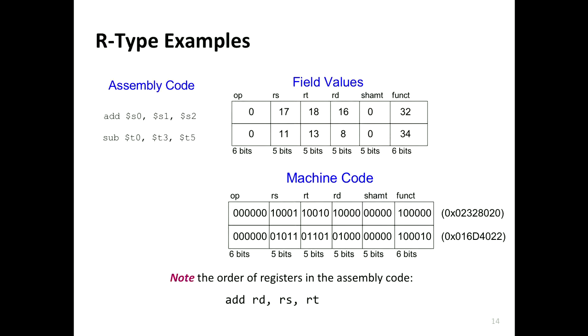What did I say? What is the register file? It's 32 registers, each register having 32 bits. Right? So what do we need? Some data in and some data out. Let's go specific into it. Now, you have S1 plus S2. You're going to write the result into S0. So you're going to read the value out from S1, read the value out from S2, and write the value into S0.